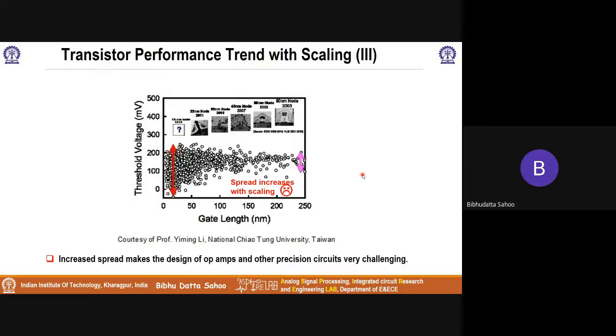Yes. Currently, I am collaborating with a company where I'm working on 7 nanometer FinFET, and the analog circuits are designed in 7 nanometer FinFETs as well. We are building a 112 gig SerDes, being designed in 7 nanometer TSMC, and we have done the TIA and all operating at a pretty good speed. There are 4 channels, and 112 divided by 4 is close to 30 gig. Each TIA is operating at that rate. TIA is trans impedance amplifier.